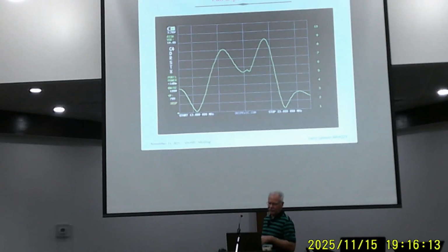The bandwidth in hertz, again, he's got 5 options there, 10, 30, I think, 100, 333, and 1,000 hertz. That just determines how accurate this is in the smaller bins. You don't need that. 1,000 hertz is good enough, and that's the fastest sweep. As you make that bandwidth smaller, it takes longer and longer to sweep across. Okay, so again, that's kind of a set it and forget it.